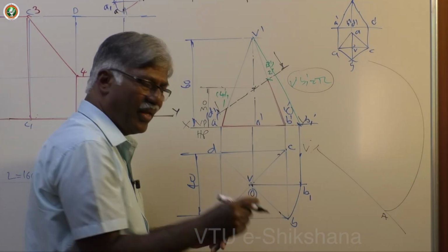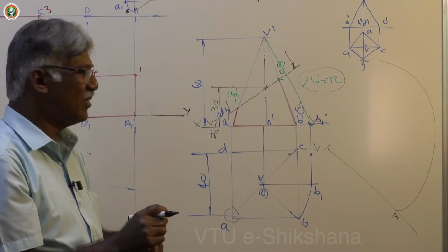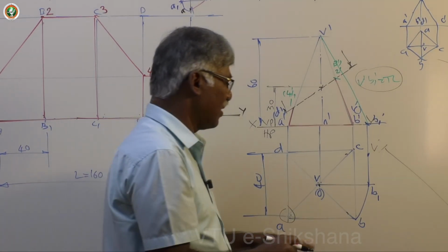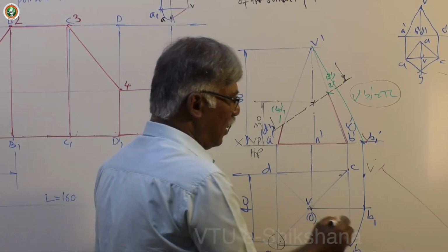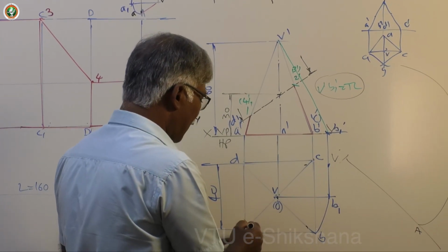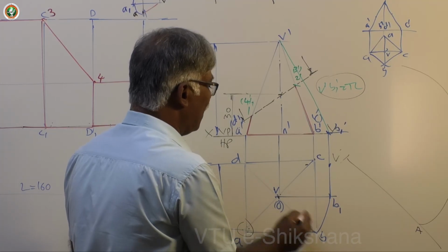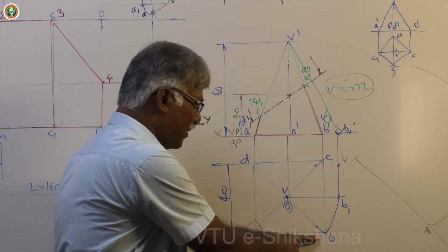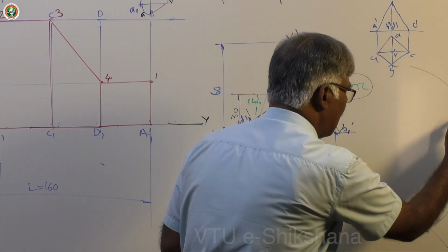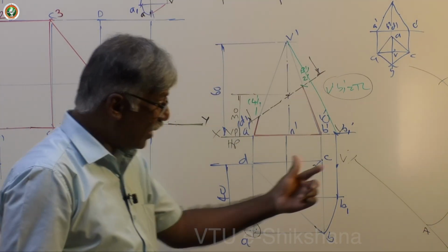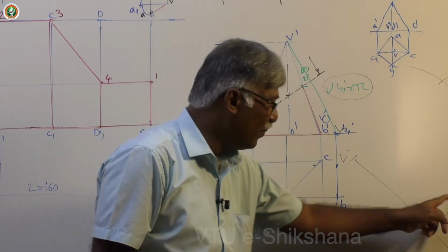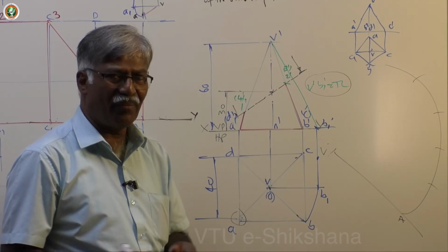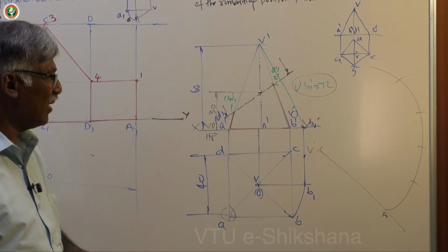Now, when I write regular pyramids and prisms and also cones and cylinders, these have a common characteristic feature: all are the same, generators and slant edges. Now what I do is I start from VA. Then I have to cover VAB, VBC, etc. You need not do it individually. Take this equal to radius with the compass manually and draw arcs. In the computer, you fix one triangle VAB and then start keeping mirror. Okay, you will get all the lines. There are many other techniques. Here, we can use mirror and do it.